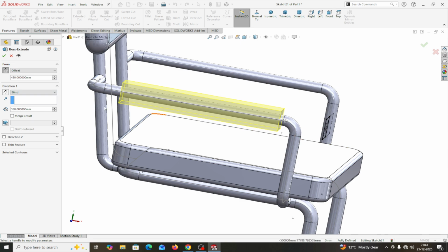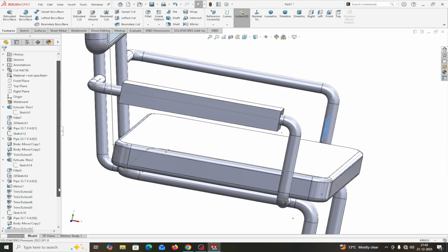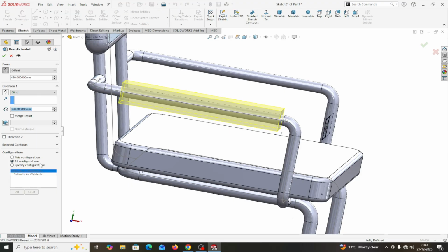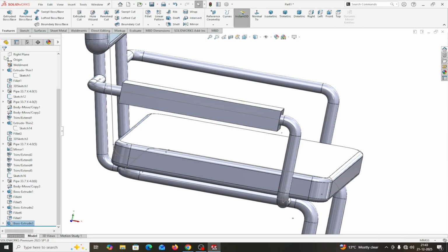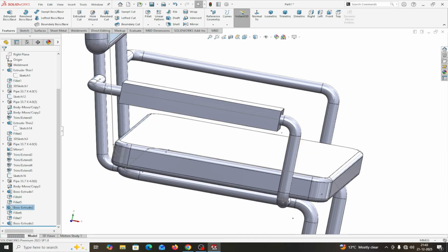Okay. If I reverse, this goes in this direction. And extrude length is 350 mm. So hit the right button. One thing more you can see, this should be unmerged. Merge and unmerge it. Make sure you unmerge this one. You also see this one, base extrude, unmerge it.